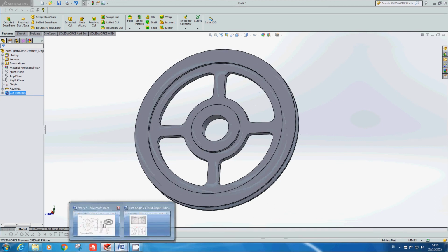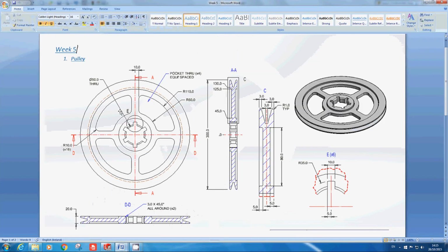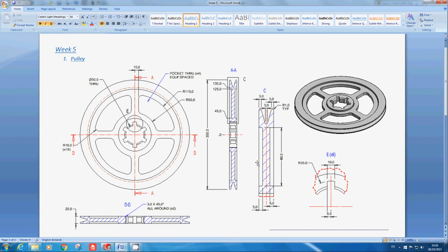So back to the sketch. So that's these 4. What's next? So next is this. Need to put in the teeth, the slots for the teeth of the spline. So again, this is another detail view here, because that'd be very small to be dimensioning and detailing. We've created a detail view over here. So everything inside this circle is view E, and it's over here.